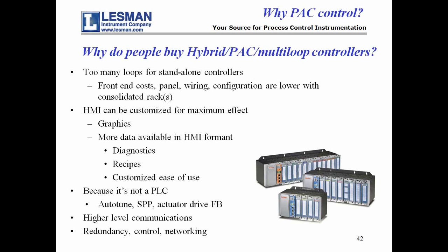There are several things, by the way, that PACs do that PLCs don't do. They always do auto-tune. They have set point programming built into them. They have things like actuator drive function blocks that just drive actuators directly without any external logic that you have to build. They always do the higher level communications, and they can do the stuff like PLCs do, which is redundancy in the networking. Then there's a category of SCADA control.